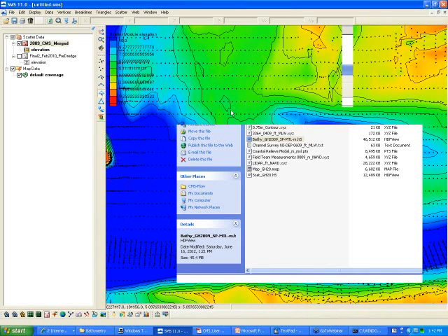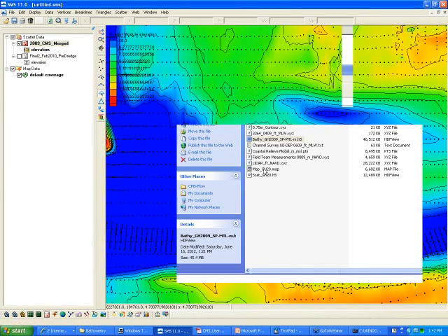One way to smooth the bathymetry is to bin the data. For example, with multi-beam data, you can bin it to a coarser resolution, and that will help remove the high frequency features, the bed forms. And when you calculate bed change, your results will look a lot better. Okay? So that's what I did here, for example.